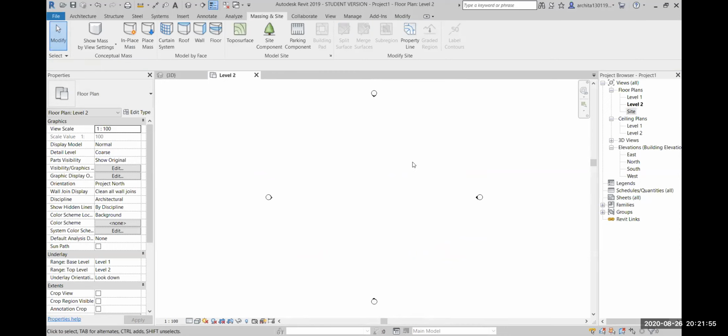Import. No, you can't. Because Revit is very specific, no? Levels and all, it is all going to be related to one building only. But what you can do is you can link another Revit file. You can have the 3D model of that file linked to your current file. So you won't have these details, but you will have the 3D part of that building.